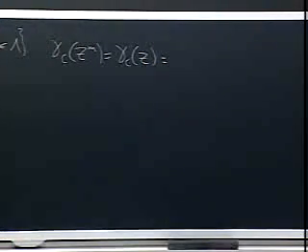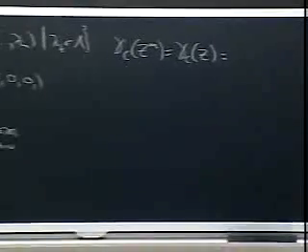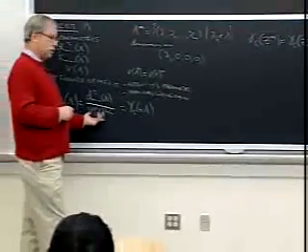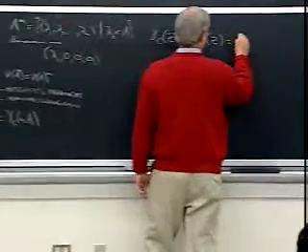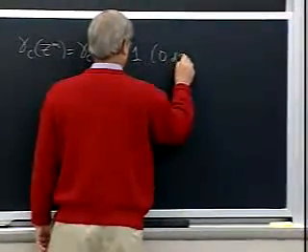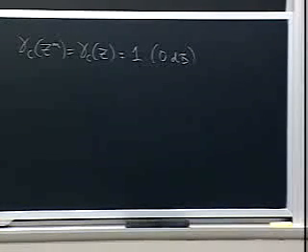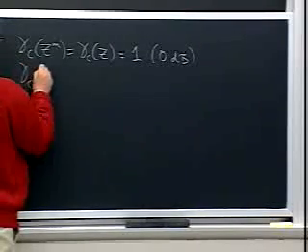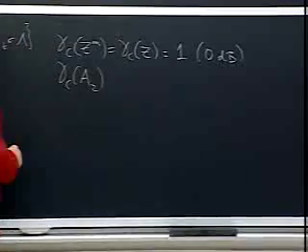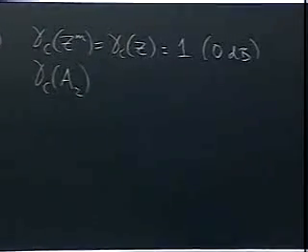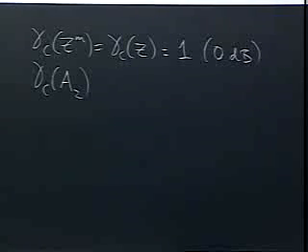I should have done this as the first example. What's the minimum square distance of z? 1. What's the volume of z? 1. So this is 1, or 0 dB. We're going to measure nominal coding gain in dB, which is, well, getting us into communications. What's the nominal coding gain of the hexagonal lattice? By asking this question, I'm basically asking, is the hexagonal lattice denser than z squared, the square lattice in 2 dimensions, and if so, quantitatively, how much denser is it?